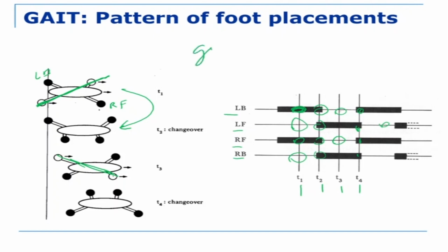So it is ground, air, ground, air, like that. Now obviously there are four legs here, right? So because there are four legs, you can either take two of them in air or you can take only one of them in air. I could have kept all three of them on the ground and only this leg goes forward. That gait is also possible.